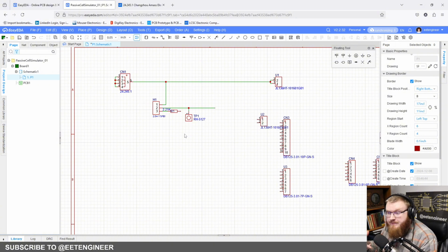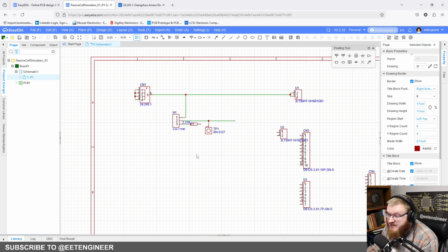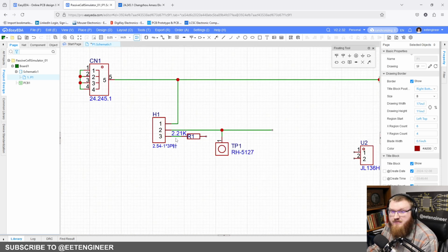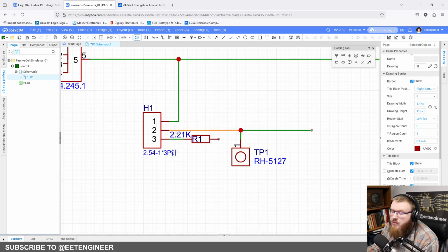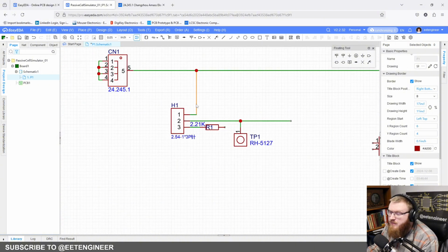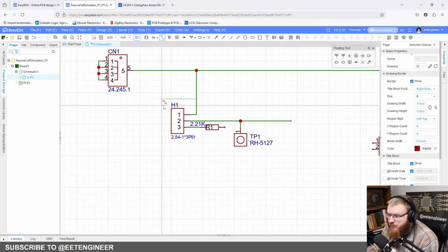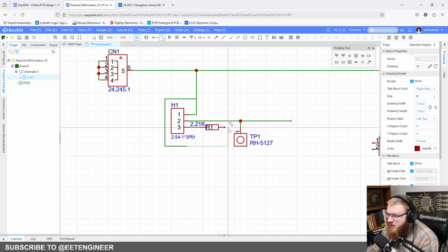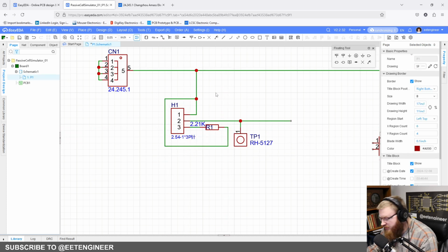It's cascading. And so that's what we're going to do here, is create cascades of resistors for a 16 series BMS. However, what if we only have a 15 or a 14 series BMS? Well, that's where this header comes in. So we're going to bring power just like this in through both ends of this circuit. So directly through one side of the header, and then through the resistor on the other side of the header, and then this is your output.